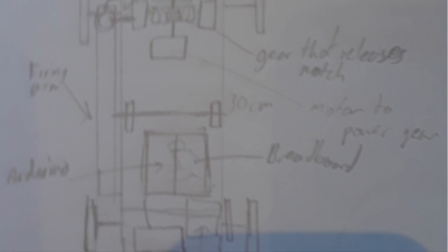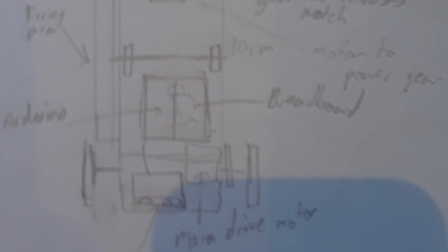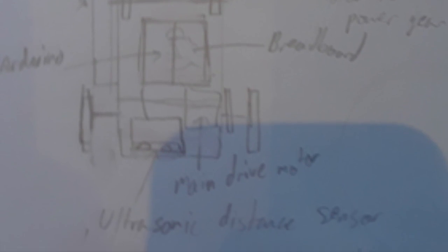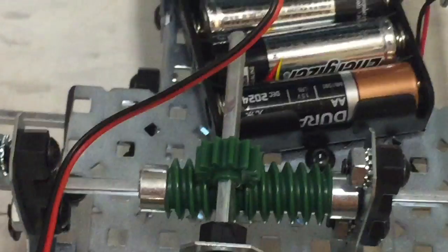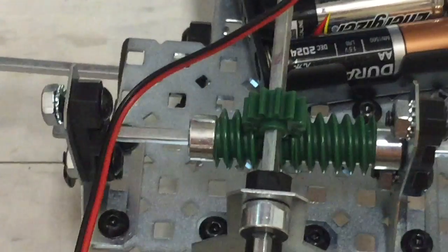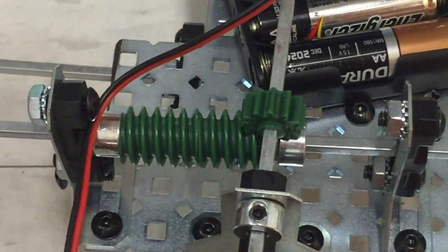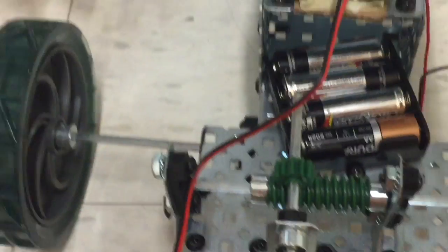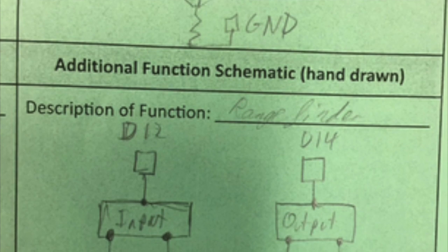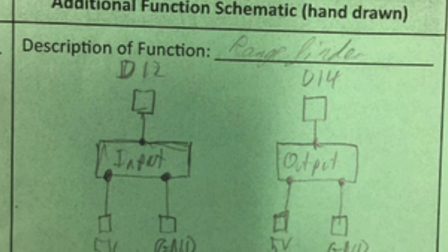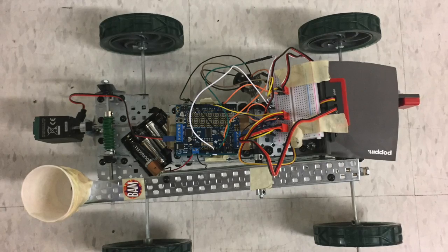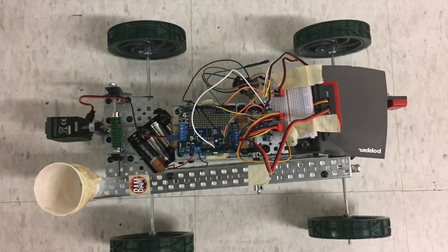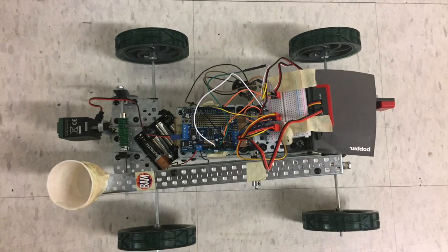My attitude towards the engineering process changed because I realized how precise engineers have to be. They have to build axle parts very perpendicular to what they go through. They have to calibrate distance sensors correctly. We had a problem where the distance sensor was reading weirdly, and it was because a metal piece was sticking up too much, and the distance sensor was reading that part. We fixed that with a piece of paper, but we had to be precise about that.